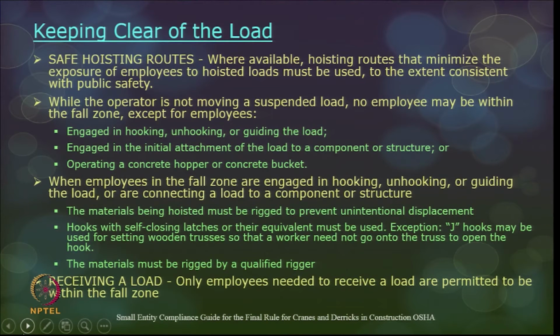While the operator is not moving a suspended load, no employee may be within the fall zone except for employees who are engaged in hooking, unhooking or guiding the load, engaged in the initial attachment of the load to a component or a structure, or operating a concrete hopper or a bucket. Only these people are supposed to stand near a suspended load because they have to guide the load. For example, with a concrete bucket, a person has to guide the bucket for pouring the concrete.